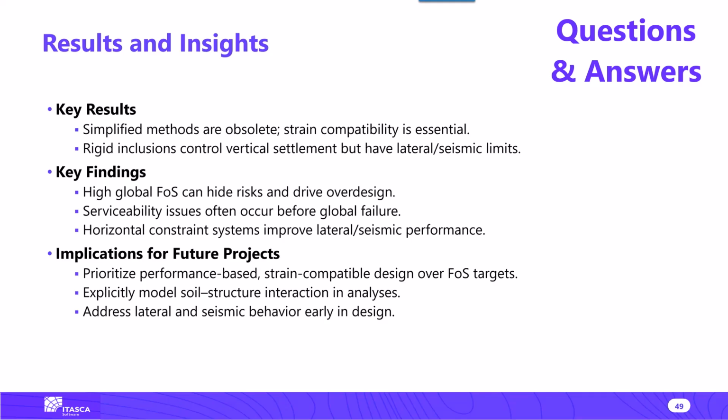And that's the end of it. So in my opinion, it's optimizing the whole construction sequence. And it's still not to be seen as a piled raft. It's still a ground improvement. The concrete LTP is supposed to crack and essentially form natural pile caps, depending on the engagement of the formation and stuff like that.